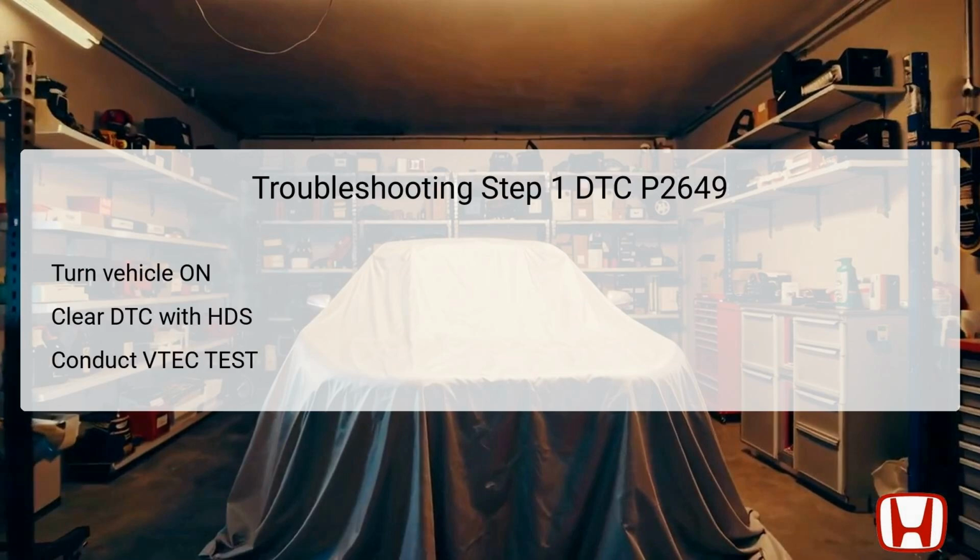Begin the troubleshooting process by verifying the problem associated with DTC P2649. First, turn the ignition to the on position without starting the engine. This initial step ensures that the necessary systems are powered and ready for diagnostic checks. Next, use the Honda Diagnostics System, or HDS, to clear the DTC. This step is essential as it resets the system, allowing for fresh diagnostic testing.